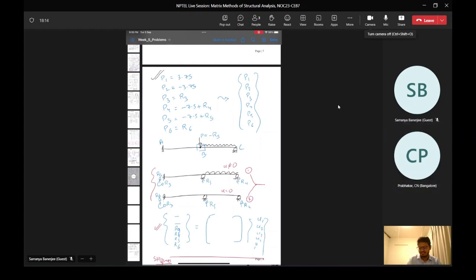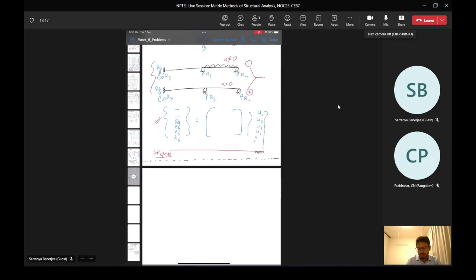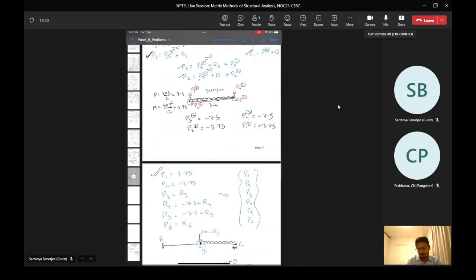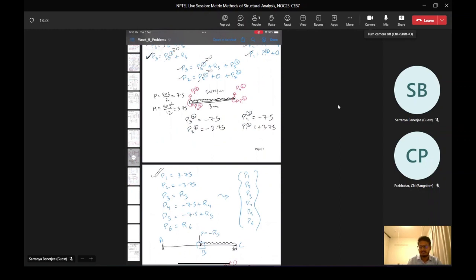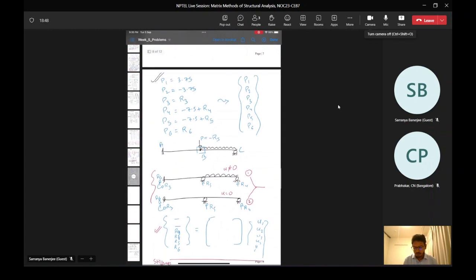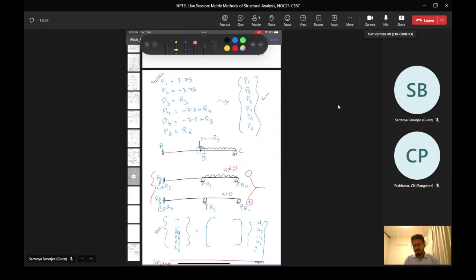Okay. So today what we'll do is we'll just take what we had found in last class, and we'll solve the rest of the questions. The majority of the question was already solved in the last class, because the main part was making the individual stiffness matrices, then assembling them, then finding the load vector, and now what is left is we need to find the different displacements and the different loads. So I could see my P vector here, the load vector. Let me write my load vector.